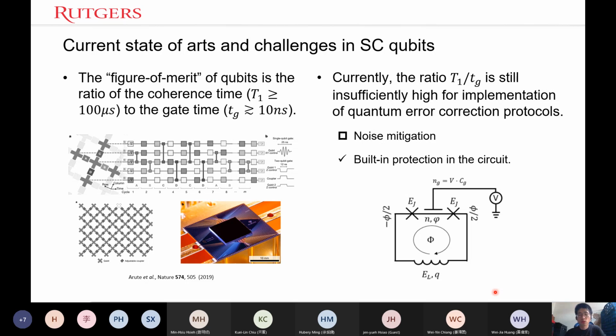But in terms of industry, just like in CMOS, we had silicon at the beginning and silicon oxide, but eventually we needed to change to SiGe, silicon germanium, and swap the gate oxide to hafnium oxide and high-k metal gate and stuff like that. So academic-wise, aluminum works well, but we probably need to do better, and we need to change in the future.